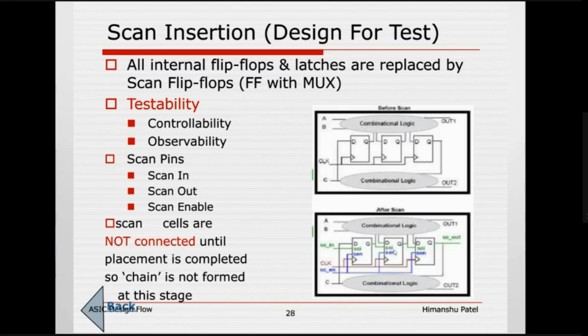Because you want to place some value at this level, at the output of this particular flop, as an input to this combinational logic gate here. Now you have to program it, right? You should be able to have controllability on each and every node. To do that, you have to have controllability on each and every flop and on primary inputs and primary outputs. That's how DFT works.